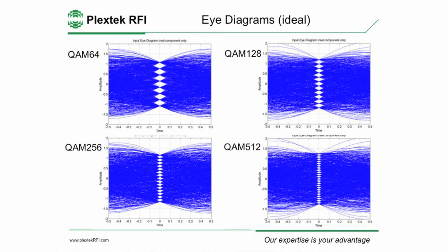Here are some eye diagrams. Now, this is QAM 64. Here you can't see what's going on. Here you can't see what's going on. So what we have, I apologize if I'm teaching anybody to suck eggs: in the transmitter, we have a root-raised cosine filter through which we pass the data, and that helps maintain the modulation spectrum to a nice tight bandwidth.